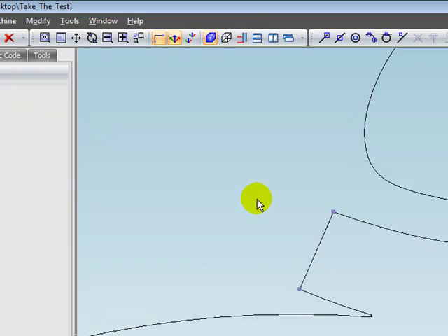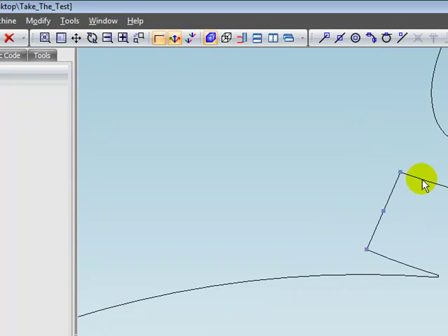So that's breaking at the ends of the previously open contours that were connected. But if I was to click there, that will now break it in two in the middle. So you can see we've now broken it up even more. And we could also use the closest snap in here. Then wherever I click with the mouse, it's just going to break it anywhere. So we're really now breaking up into lots of little pieces here.